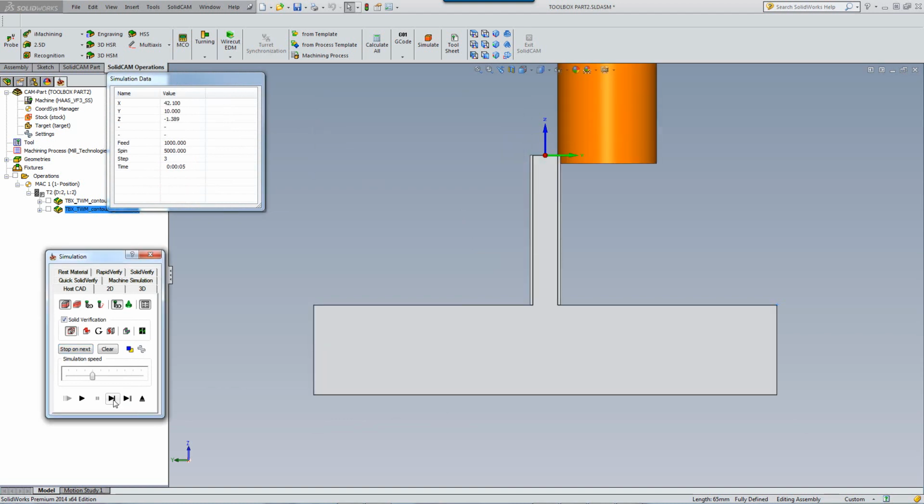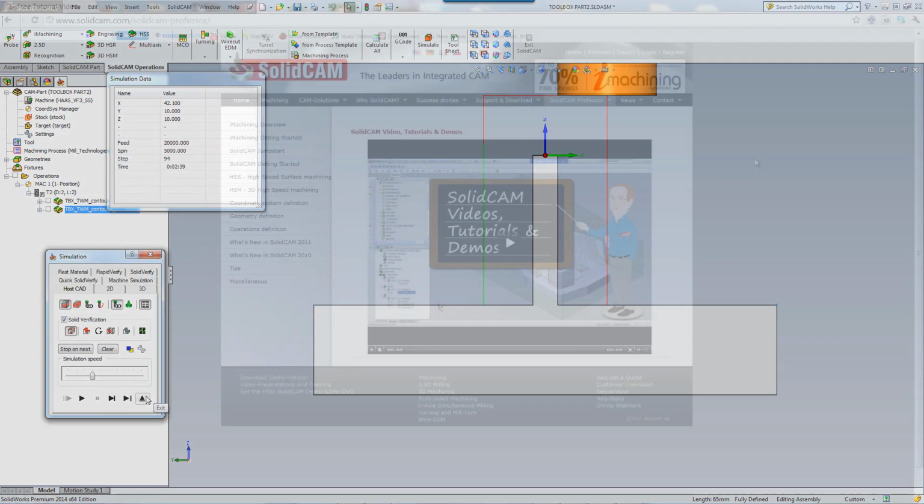It has its first step down over here. Note, it did not go down 3 millimeters, but this value over here instead. And next, it'll go down to its 3 millimeter step down. And note that every single side, it's going down more and more, always leaving a little support on each side as it's cutting down on the part itself until it reaches the very bottom of the part.